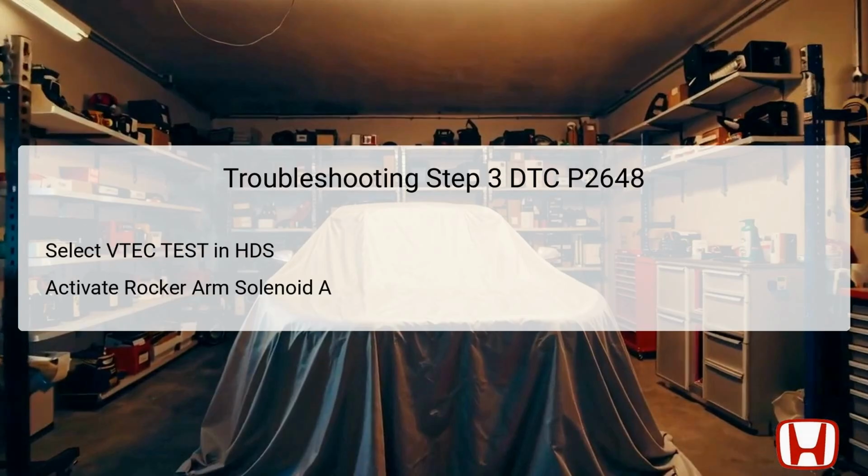In the third step, the technician selects the VTEC test option within the HDS interface. This function allows for the activation of the rocker arm solenoid A, which can help determine whether the solenoid is functioning correctly under controlled conditions. By sending a direct command to actuate the solenoid, you can check for its response, ensuring that proper oil flow is established when activated.